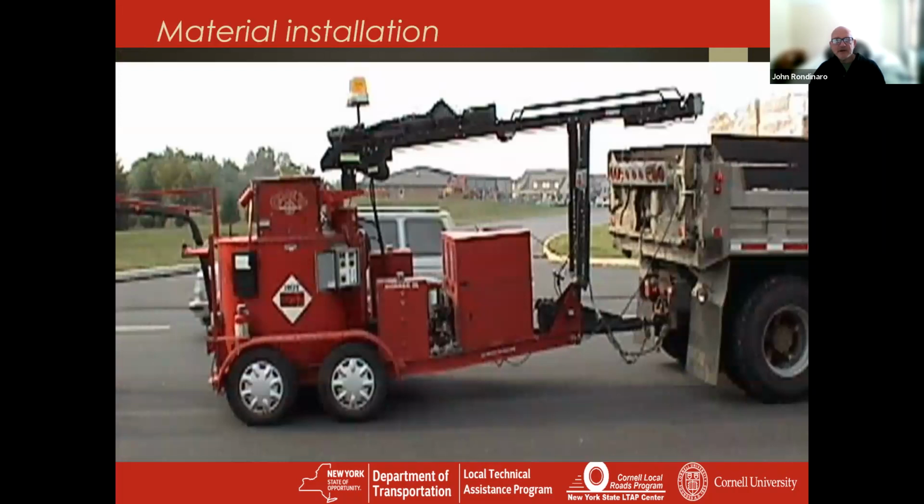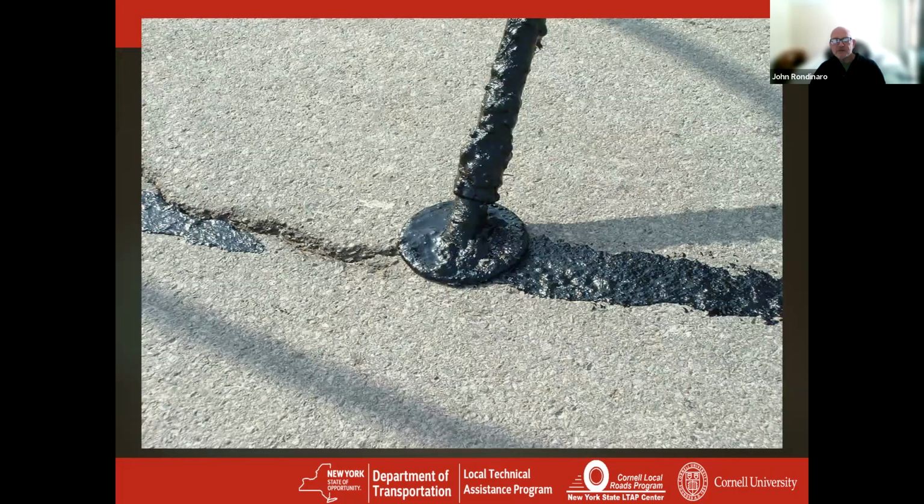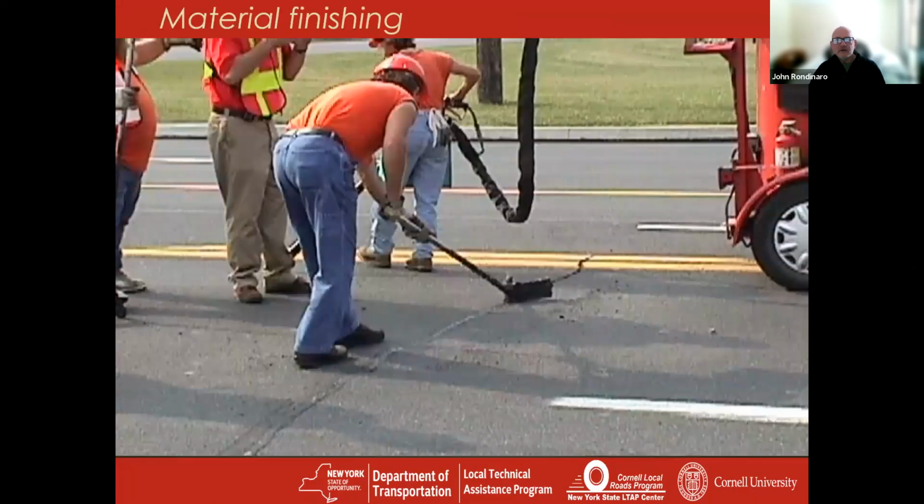This is a typical crack sealing rig, towed behind, and this is just a typical wand and disc setup. It squeezes the material down into that nicely prepared crack, and then leaves a nice thin film of material. It's not an overband at all.